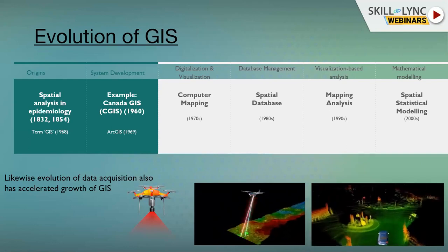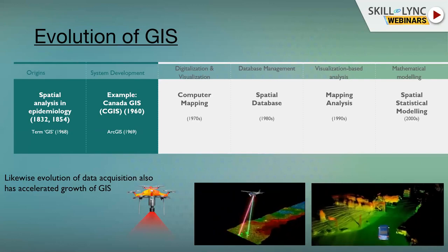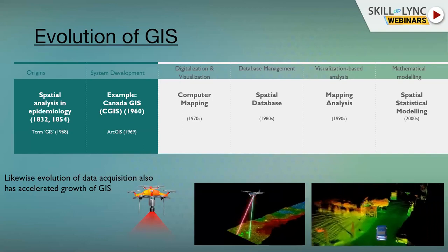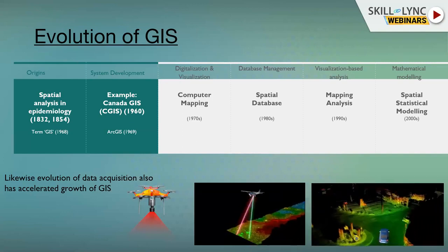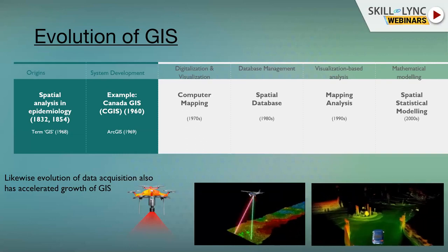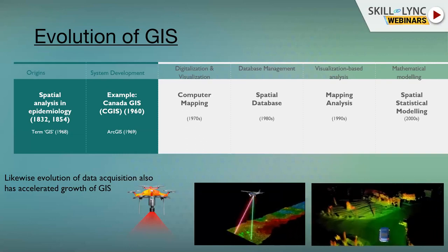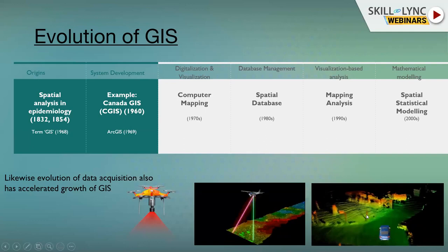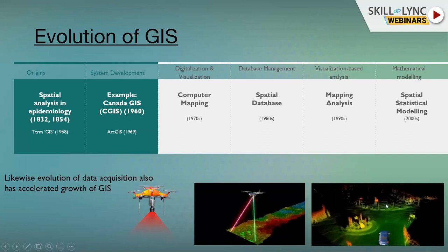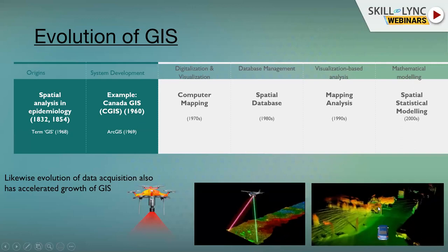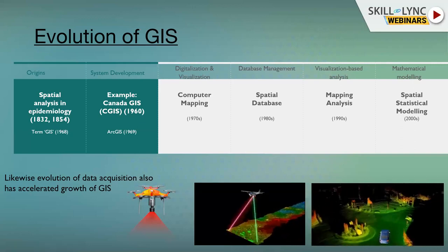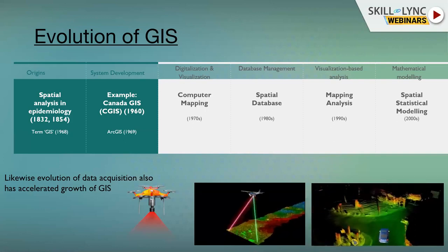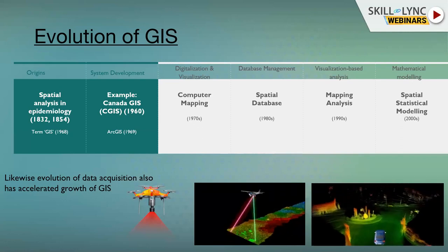Lidar data is the current buzz for GIS, because it's able to give you more accurate data. For example, if you want to apply lidar onto utilities, if you just do a mobile lidar survey, you are able to see the sag in the electrical lines, right? You're able to see the sag. So it helps you understand the risk, and whether it is eligible for the transmission line to come that low. So that is the accuracy lidar is going to give.